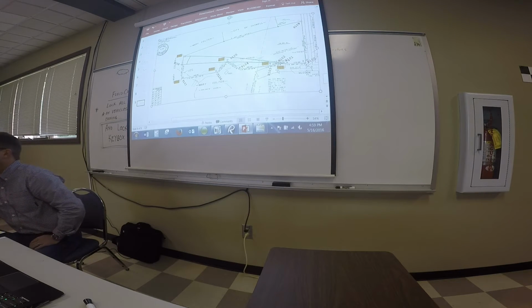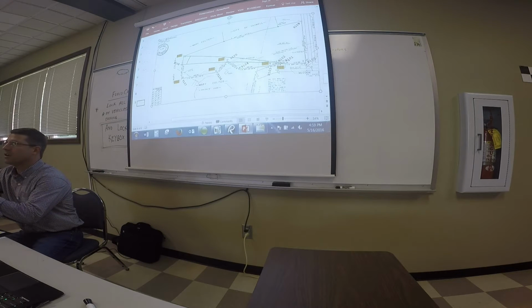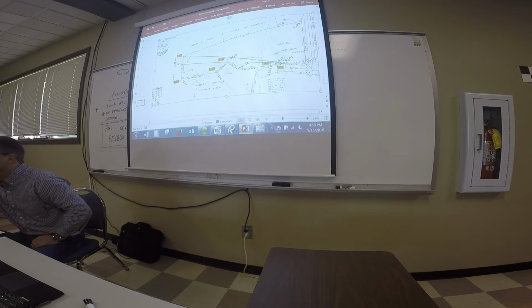Way back in the day, we shot a lot of pads in CC1, CC2. We may shoot 3 sides of something, and we wanted somebody to know that it's not just an EC. We wanted to know that it's the actual corner of a piece of concrete. So you might have EC1, CC1, and that's when we were mainly drawing things by hand. But with field to finish, there's no use really for a CC code. It would be edge of concrete 1 at the corner, and just shooting it at the points that it needs to be shot.